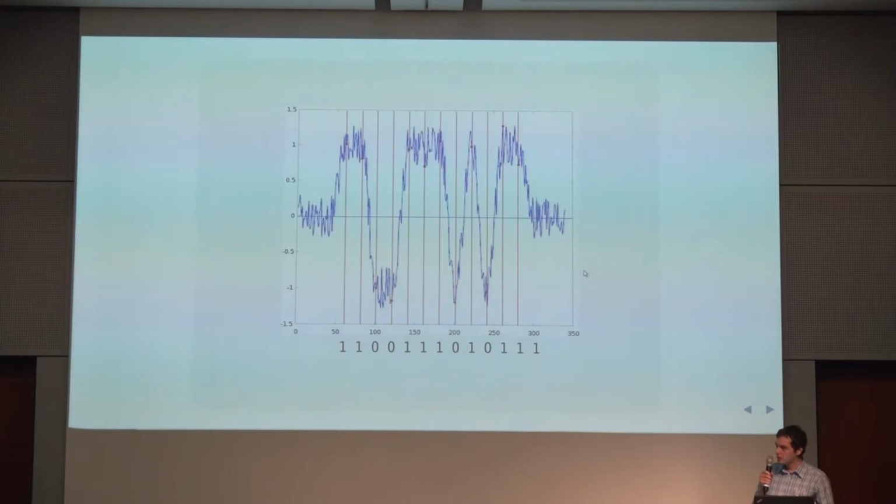And okay, we have that single signal, and the next problem is that it's still a bit oversampled, and we need to decimate it with the correct phase offset, finding the samples corresponding to the maximum power point of each symbol.